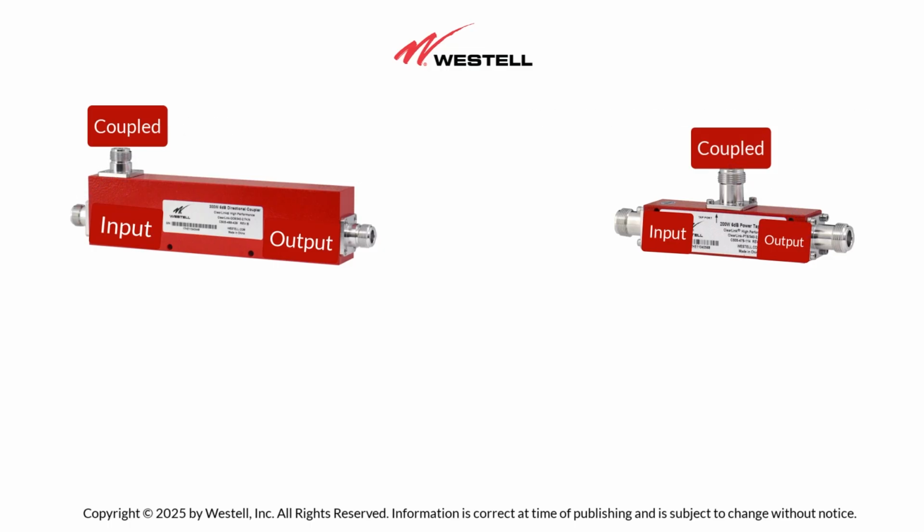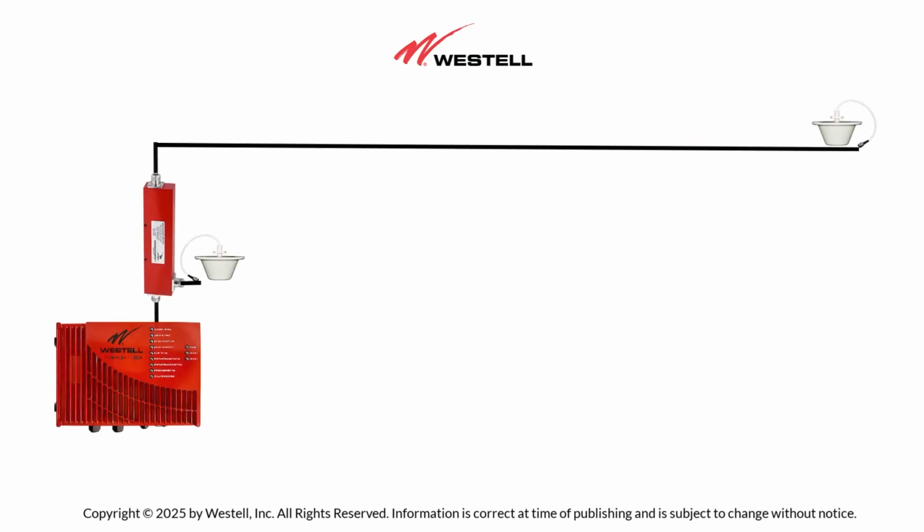One significant difference between a tapper and a directional coupler is their directionality. With a tapper, a signal can enter either the input or output port, and the coupled port will output a signal at its specified attenuation value. In contrast, in a directional coupler, the output port and the coupled port are theoretically not connected. This means that any signal entering the output port will not exit through the coupled port, and vice versa. In practice, some power may leak out, but this is usually 30 to 50 dB lower than the original signal level. Because of the directional coupler's directionality, it is very important to install it correctly.